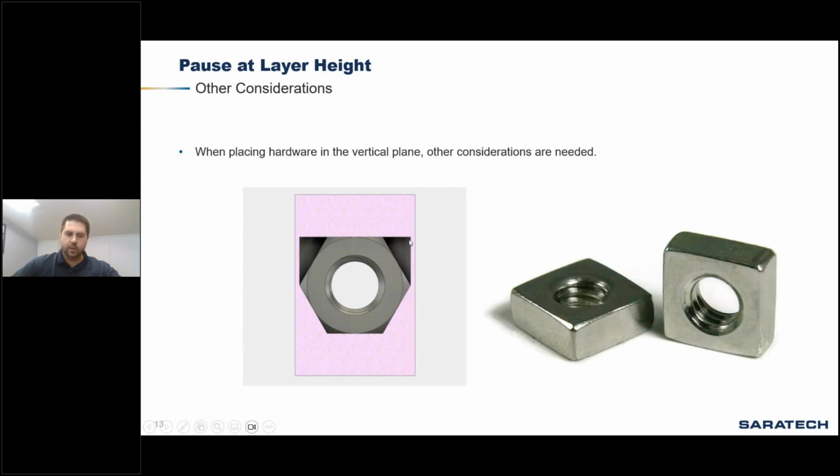Another note too, magnets are a really fun thing to embed in your parts. We've made some cool snap together cases or parts that snap together with hidden magnets in there. I will caution you on this, and I didn't know the first time around. Obviously the print head is made out of metal and it is a ferrous metal. So if you insert a magnet into your part, the print head will stick to that magnet and pull it straight out of the hole.